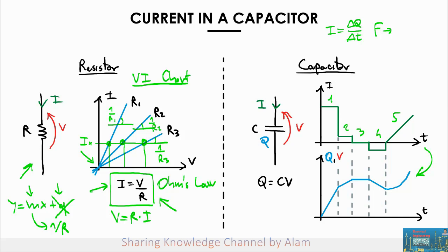Now the capacitor can be represented as a tank with a certain amount of water inside, and the volume of the tank is the representation of the capacitance, while the height of the water, the level of the water, is a representation of the charge. This hydraulic example should allow us to get the behavior of the charge, at least qualitatively, for a given waveform of the current.